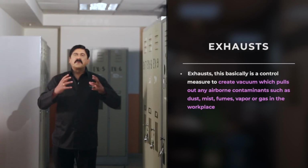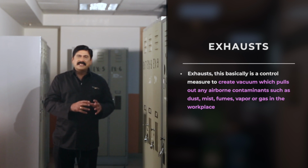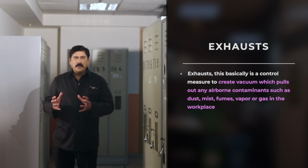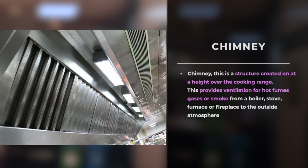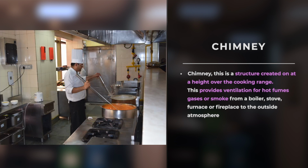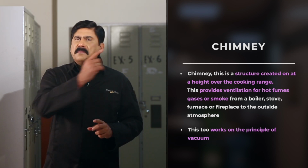Artificial ventilation is further divided into four types. Exhausts: this is a control measure to create a vacuum which pulls out any airborne contaminants such as dust, mist, fumes, vapor or gas in the workplace. Chimney: this is a structure created at a height over the cooking range. This provides ventilation for hot fumes, gases or smoke from a boiler, stove, furnace or fireplace to the outside atmosphere. This too works on the principle of vacuum, same as the exhaust.